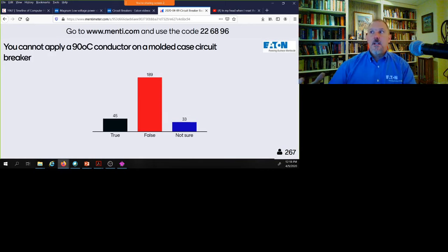So when you think about conductor ampacity, we first have to consider the conditions of use and go through 240, calculate it where you assume 85% of continuous loads, et cetera, and then you do the same thing where you don't consider that, but you look at another aspect of the parameter.